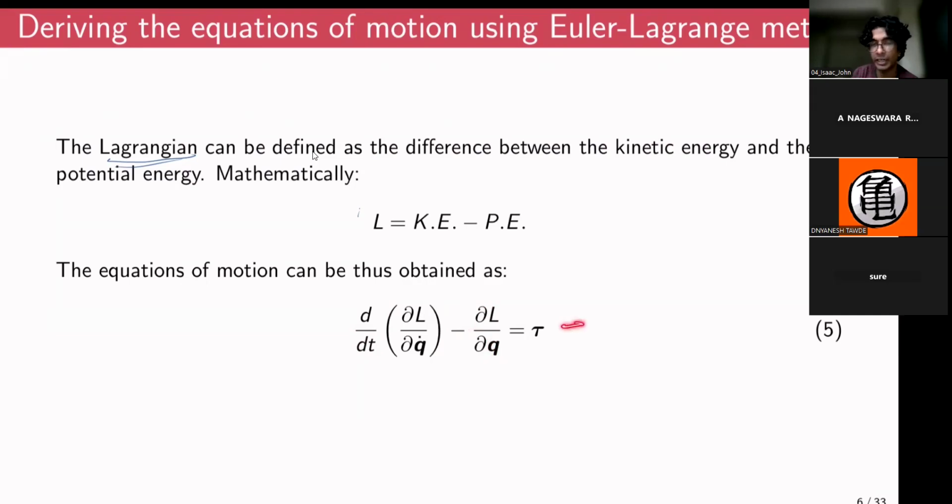So this is essentially a vector equation. Depending on the kind of robotic manipulator that you are investigating, the vector Q can have multiple joints. If you are dealing with a 2R robot, Q would be theta1 and theta2, which are the generalized coordinates that fully define the configuration of a robot.